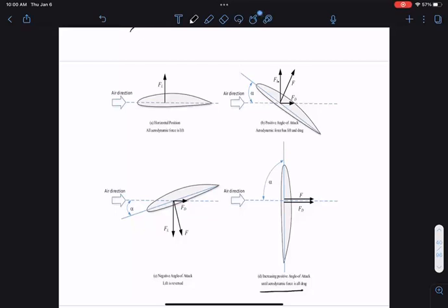Things move very slowly. You're not going to ask a nuclear generator to back off generation to accommodate wind. Even gas is not fast enough. As we go along the course, you'll see the way we deal with this is we put a big resistor close to the turbine. If you really have to burn power, go through that resistor. You may melt something, but at least you don't have a catastrophic failure. But nowadays, people are replacing that with storage, so the power goes somewhere.